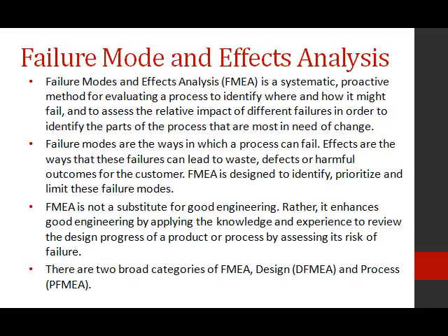This approach is not a substitute for good engineering. Rather, it enhances good engineering by applying the knowledge and experience to review the design process of a product or processes to assess its risk of failure. There are two broad categories of the failure modes and effects analysis, which are design and process effects.